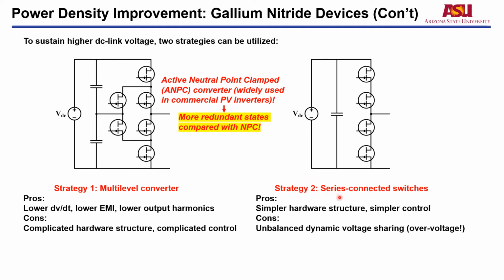The second strategy is the series connected switch strategy. The pros for this strategy include the simpler hardware structure and simpler control. The cons include the unbalanced dynamic voltage sharing, which may cause overvoltage for the low voltage rating individual device.